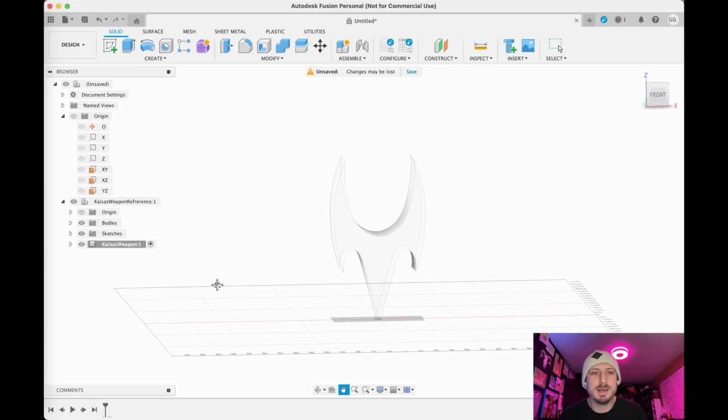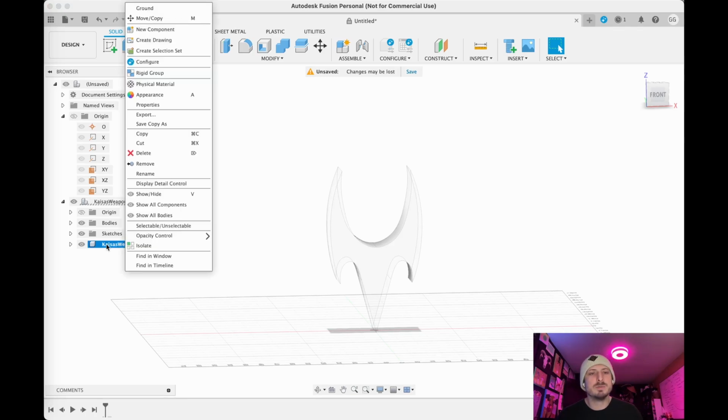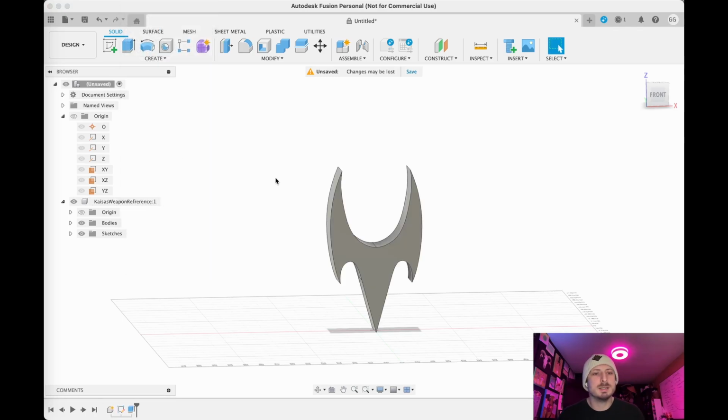And notice that when I created that component, it just created it within the reference component. So it kind of became a child of this component. I didn't want that. That was a mess up on my part. So you could actually right click, delete, and right now, you'll see if you highlight one of your components, you have two options.